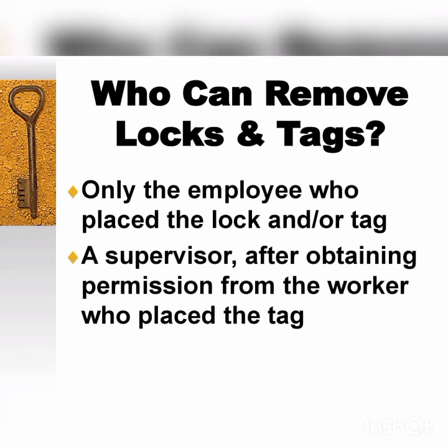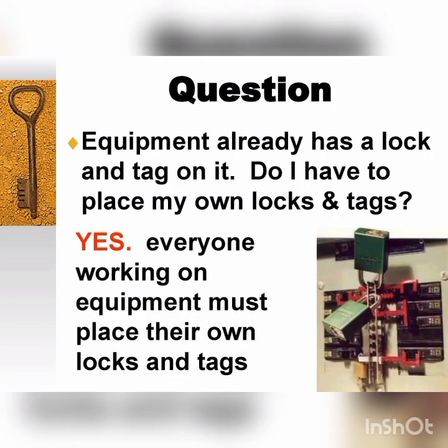Who can remove the locks and tags? This is the most important thing. Only the employee who placed the lock or the tag is allowed to remove it. A supervisor, after obtaining permission from the worker who placed the tag, is the only other person authorized to remove the tag. If you have equipment which already has a tag, you can apply your tag on it.